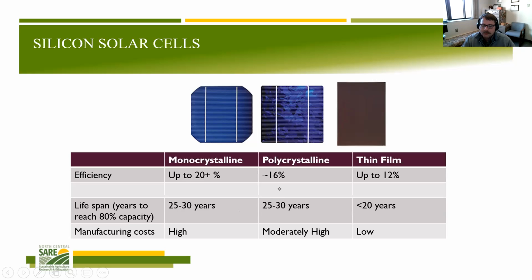Really, if you can get a price per unit power that's low, having it be just slightly less efficient is okay, especially when space isn't limited. I'm not trying to generate a certain amount on a certain small roof. If you have a small roof and want to maximize production, a monocrystalline is going to be able to do that for you. If you're just trying to offset some of your load, the lowest price per watt is going to be what you want.